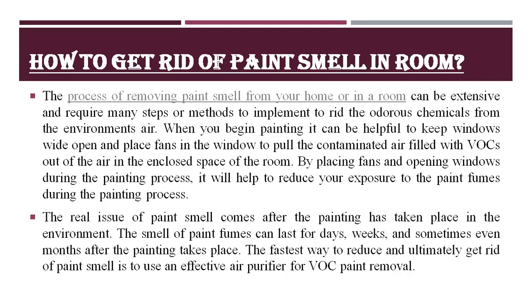How to get rid of paint smell in a room. The process of removing paint smell from our home or in a room can be extensive and require many steps or methods to rid the odorous chemicals from the environment's air. When we begin painting, it can be helpful to keep windows wide open and place fans in the window to pull the contaminated air filled with VOCs out of the enclosed space of the room. By placing fans and opening windows during the painting process, it will help reduce exposure to the paint fumes. The real issue of paint smell comes after the painting has taken place.